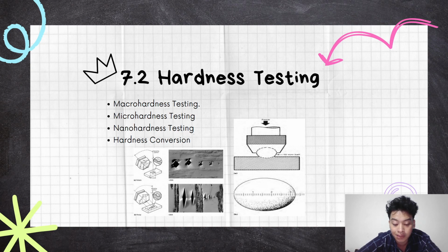Hardness testing may be classified according to various criteria, such as the type of indentation measurement, performance or area or depth, magnitude of the indentation load, and the nature of the test: static, dynamic or scratch test. For example, the measurement of the indentation area is used in the Brinell and Knoop hardness tests. In contrast, indentation depth is measured during the Rockwell hardness test.